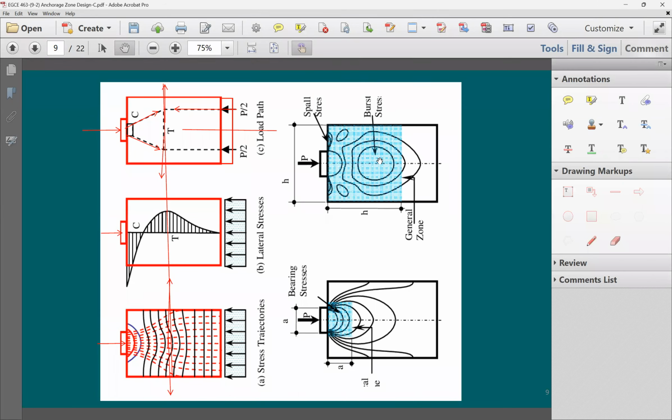If you'd like to do some elastic analysis, you can also end up with the same distribution that you're looking at here. Look in the middle. This contour line is going to be referring to the highest stress. And then it just goes down and down once you get away from this point. You see it goes down this way and also it goes down this way. And at a certain point, you're going to have here zero stress. And then you're going to start to flip into the compressive stress. This here explains the stress distribution in the Y direction.